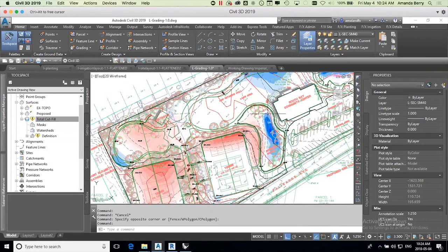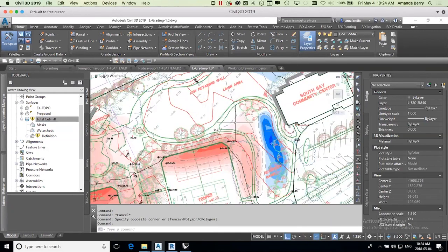And what I've done here in the elevation banding is I have told it to every 0.25 of a meter, you could do it every 6 inches or every foot. I actually, even though I work in metric in Canada, I used to put these intervals at 0.15 of a meter, which is 6 inches, because the contractors were better able to understand that because a lot of the contractors grew up when Canada was in imperial. So it's really easy to mix and match that way.